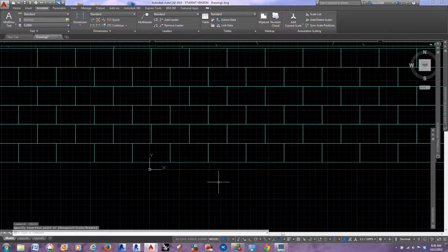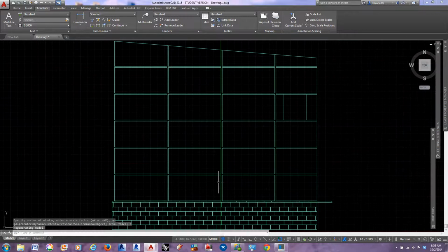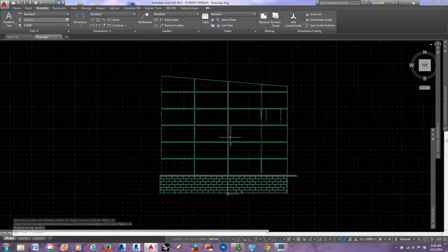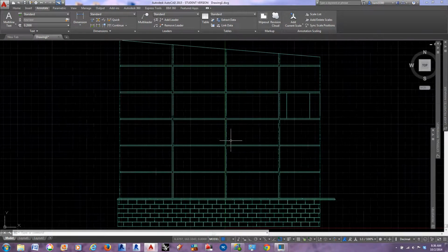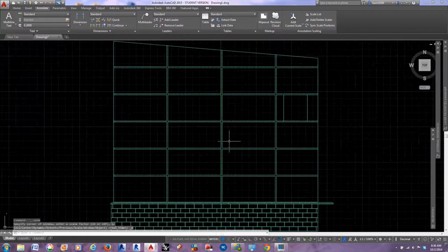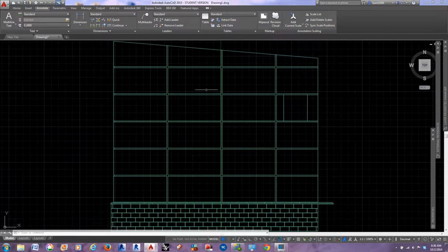We're going to place it, and I'm going to type in Z, enter, all, A, enter, and it should zoom out to the entire thing that is in there. And you can also double click the middle mouse button, and that'll zoom to extents as well, which is just basically whatever elements you have in here.